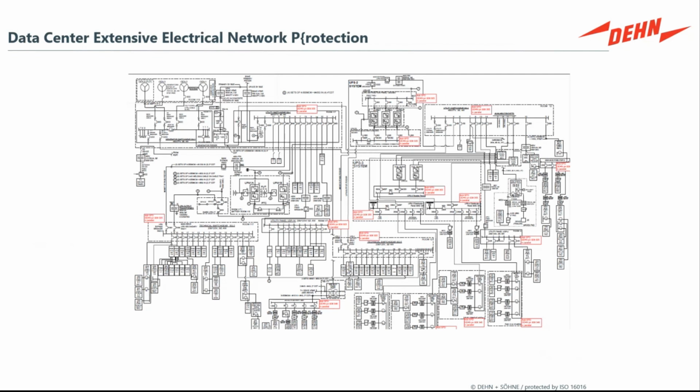And there's a lot going on here, but this is a really good typical example of data center complexity, where you have multiple sources of power, backup diesel generators, several levels of generators, utility power with A and B feeders, transfer switches throughout where you have the power source adequately transferred over, multiple levels of surge protection, and then the ideal is that you get right in next to the actual victims inside the structure, the computer systems, the rack systems, the power delivery racks that are spaced throughout the data center, and apply surge protection directly on them to create that electrically stable environment.